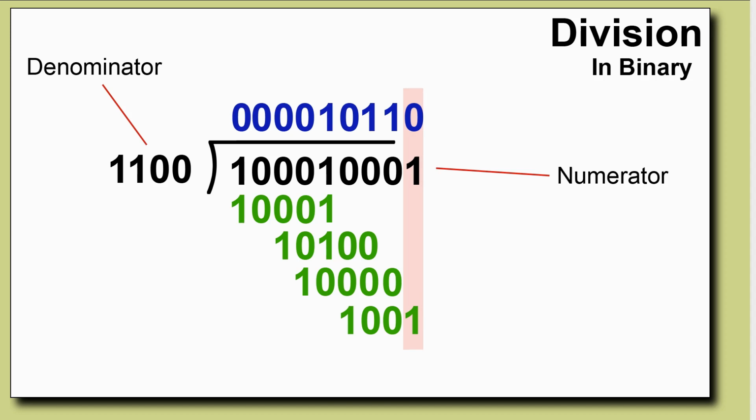This is looking pretty good. Now, a crucial element here that I do want to draw your attention to is every single time we were looking at a digit, we were only looking at that singular digit in the numerator in order to generate the output digit in the result. And this is a particularly useful property for us to have. So if we would say dividing a 16-bit number by an 8-bit number, we don't need to look at the entire 16-bit number. We want to scan through it 1 bit at a time.